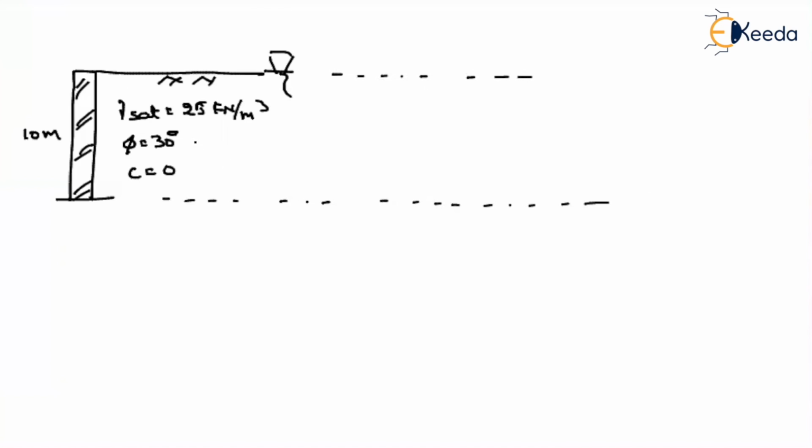Now tell me, what is the difference between the dry soil and the submerged soil? If you take any point in the soil mass, soil is there, and also in between the pores, water is there. Do you think lateral earth pressure for water and soil are the same? No. Why? Because for water, in all directions the pressure is the same. But for soil, in all directions you cannot say the pressure is the same. So we have to find out the stress due to soil separately, and the stress due to water separately. Let us say, because of the soil only we are finding.